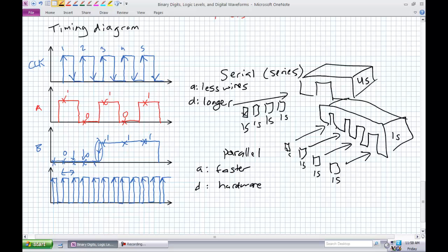Think about ways to do that. Don't take the same color wire. Don't take 8 orange wires. Maybe you could take 8 orange wires and label them A0, A1, A2, A3, A4, A5, A6, A7. Or even better, use the resistor color code. Take different color wires. Think about what is 0, 1, 2, 3, and so on in the resistor color code: black, brown, red, orange, and so on. Maybe use these wires. You'll know visually how those things work in a parallel system.